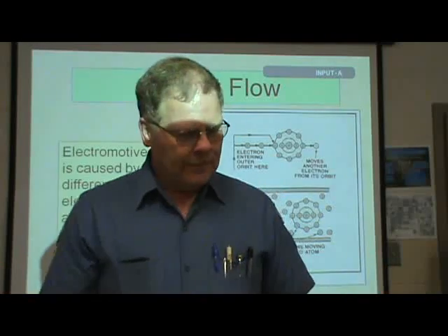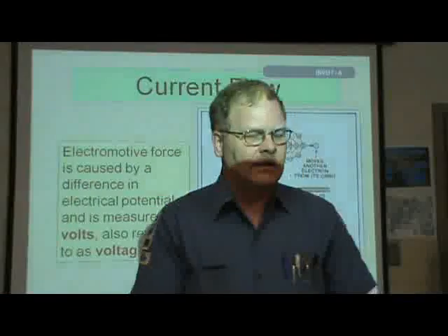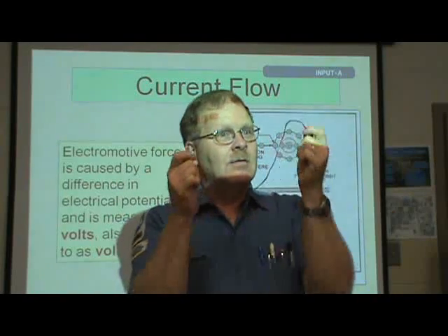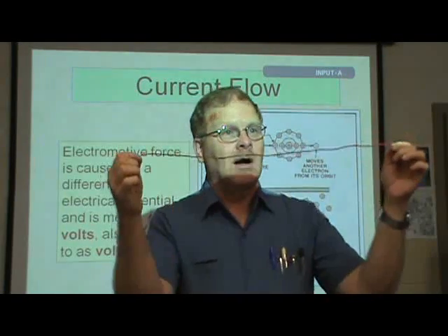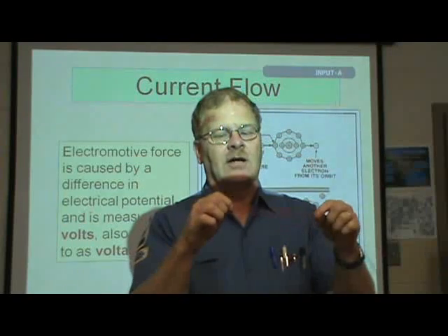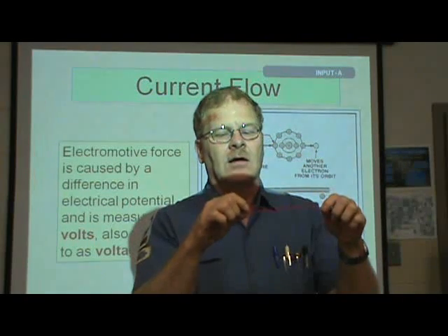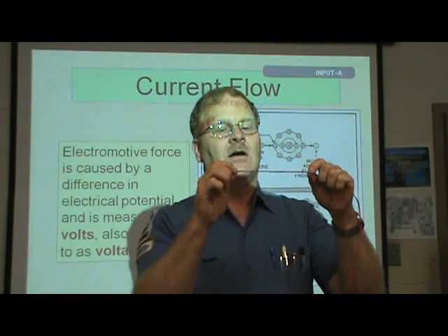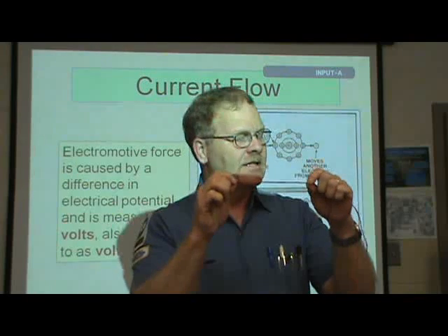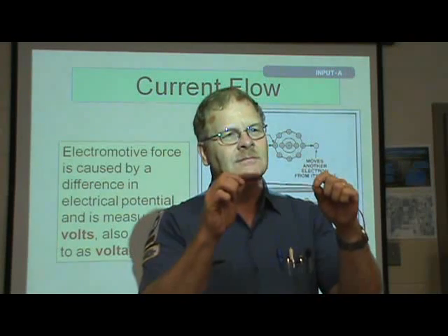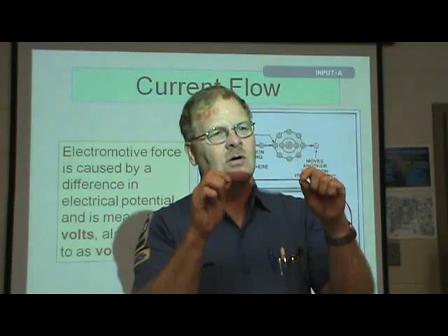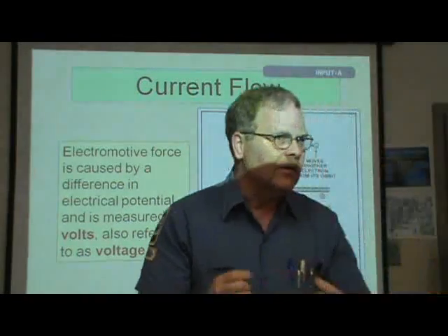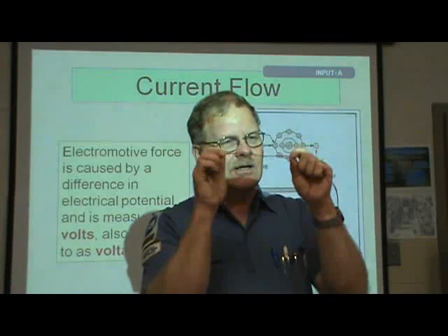If it's a piece of wire, like what happens here, Brandon can answer this question. If I hook this up to both sides of a battery, what happens to the jumper wire? It becomes a load. It turns into a little smoke bomb. This wire here has actually been heated up one time. I can see where it's melted off. You can take a piece of wire that long, and if you short something out so that it burns the insulation off, it'll fill a whole car up with smoke. And it ain't really good to breathe that smoke. You probably need to roll the windows down because it's poison. But the fact is, one little tiny piece of wire will fill that car up with smoke.